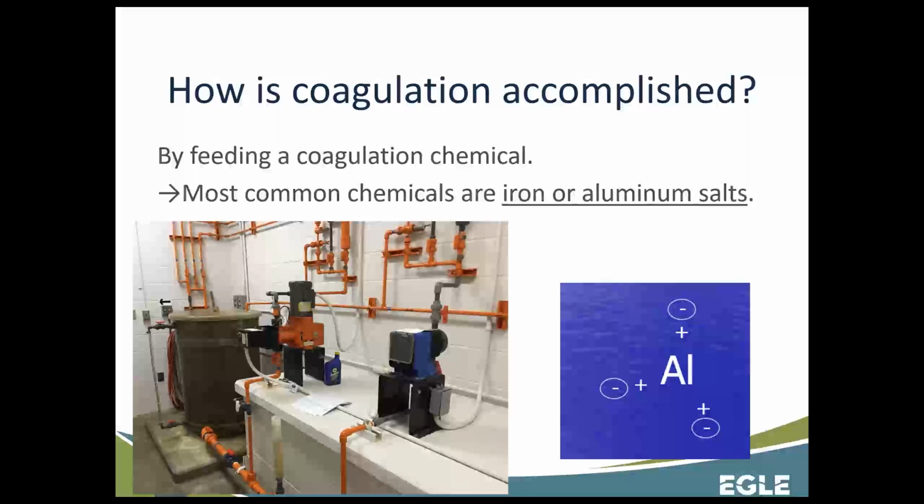It's just convenient. If you have to switch right away, you can have the settings all set identical pretty quickly. It's also nice to have the same pumps just for parts and pieces, and everybody knows how to work on them. Just one more thing that you're going to have to know how to operate and fix if you have different feed pumps, but obviously it's just inconvenient. It's not impossible or anything.